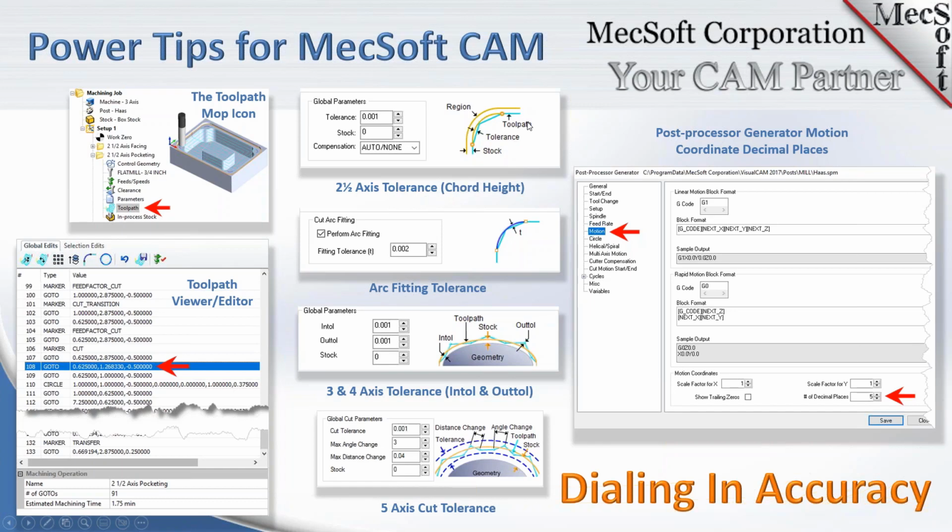Toolpaths by definition are linear, so your CNC machine interprets points, going from point to point to point. Initially, those points are connected by straight lines. If you want to have a curve or an arc for a smooth transition, as a real arc, then you can fit arcs to those points in the toolpath. And the tolerance that you see here is what is used to calculate the number of facets as it goes around a fillet or any curvature of your part. So the tighter the tolerance, the more facets that will fit in that curve.